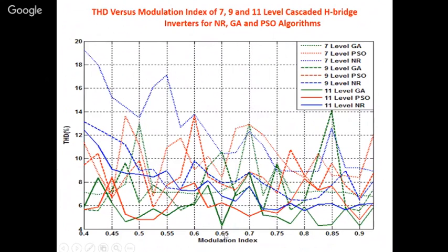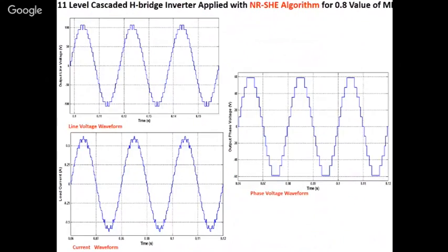But if we take 0.65 as the modulation index, what will happen? Your output voltage will be less. So 0.9, in the sense, is almost towards 1. Say 240 was your aim. So you got 230, that is good. If you get only 130, you will not take it. So 0.65 is a modulation index, 0.9 was good. So for 0.9, we will be finding all the THD, and we will try to keep the system at that 0.9 modulation index. So here all the THDs were found.